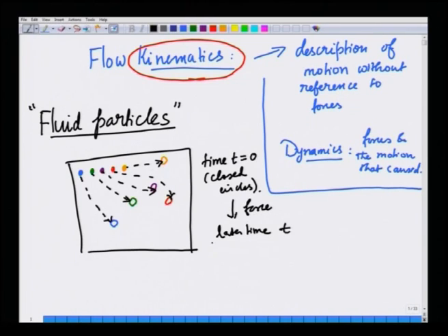Okay. So, we are assuming that the dye molecules are not diffusing, or the diffusivity of the dye molecules is so small that for our time scales of interest it is immaterial that the dye is diffusing. So, the dye faithfully represents a point in a fluid, okay, to the extent that you can resolve a point with the help of a dye drop, and this dye drop which you are using to identify a point will in general evolve in time upon application of forces, because the fluid is moving.